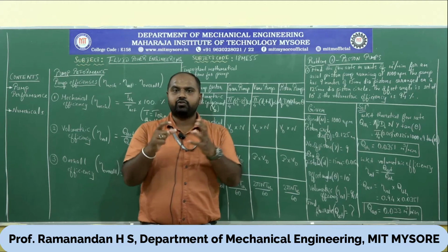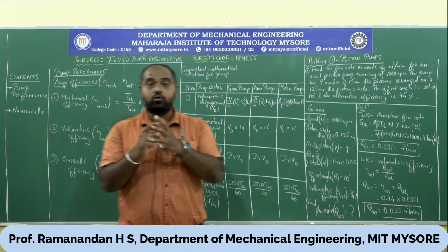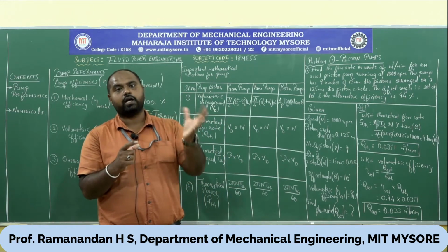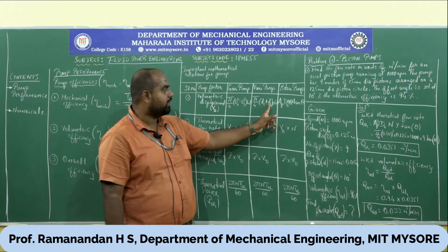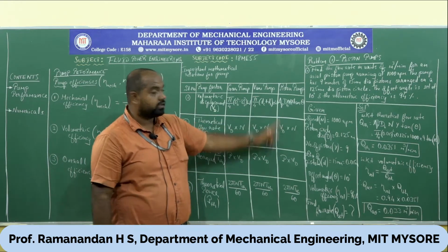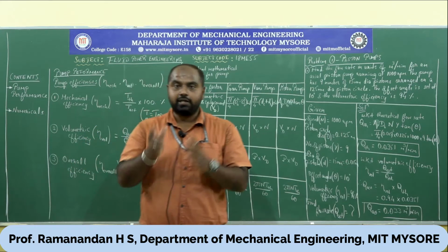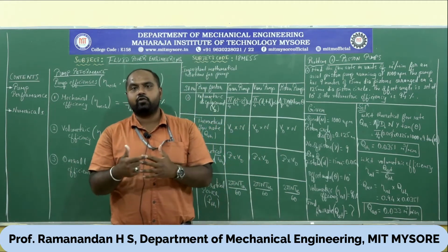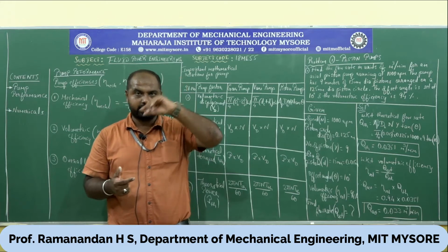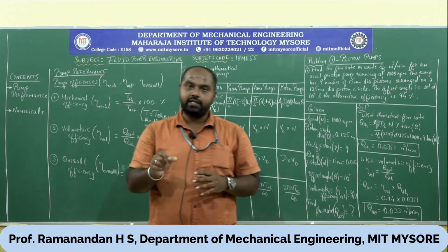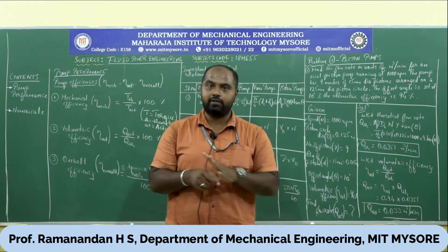The space between them is the addition of these two, DC plus DR, the diameter of the cam ring plus the diameter of the rotor, into the eccentricity between these two, because to generate the centrifugal force we need eccentricity. We have seen in the pictorial representation of vane pumps that eccentricity is required for creating the centrifugal force.